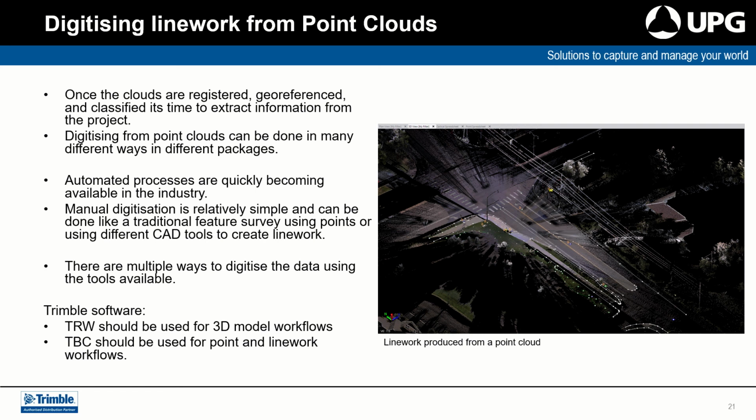There are some automated processes which are quickly expanding, and there's also some manual processes which are more like the traditional survey techniques that you would find out in the field, where you create CAD points against scan data and give it a feature code. These multiple different ways are vast, and you don't have to use one technique within the scan data, you can use multiple techniques when processing the data.